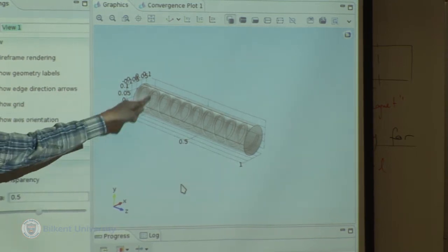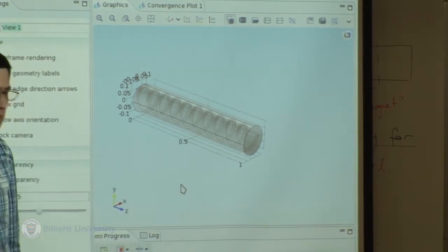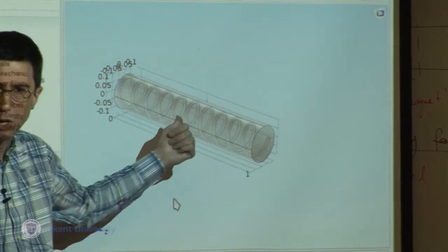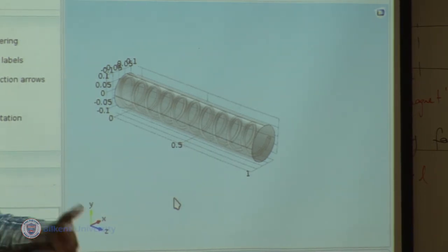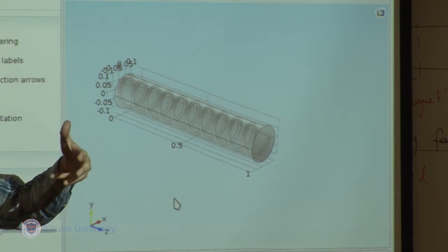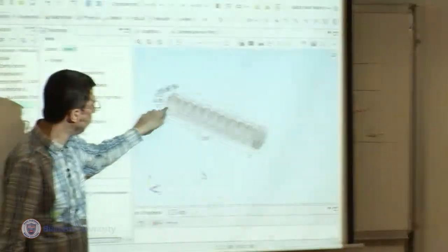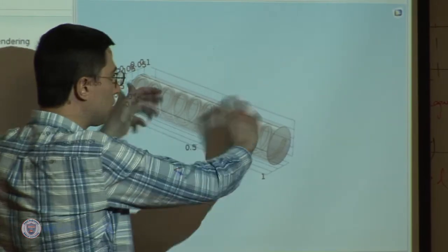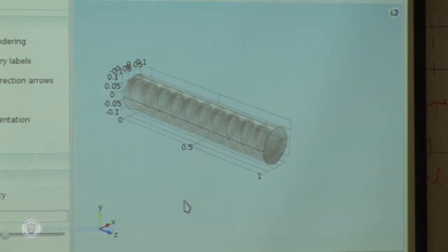The trick is that I put a helix in the cylinder. The cylinder itself, the matrix, let's say, is of a certain Young's modulus. The helix is much stiffer, 1,000 times stiffer. There are production methods to make a hull, a cylinder with a hollow inside, more resistant against torquing, where you wound a fiber material around it in some fashion. That's what I'm trying to represent. So this thing perhaps would be stiffer against torsion because there is a very stiff torsional structure inside it. But I'm not going to torque it. I'm going to pull on it.